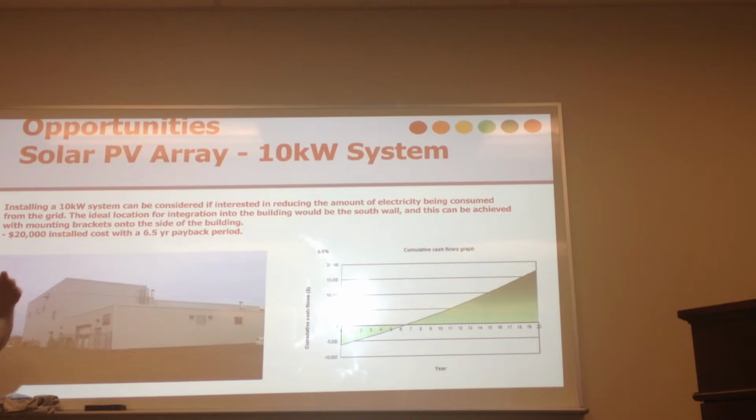And then, like I said, what did you calculate yesterday? Capacity factor. For your information, these people are going to love to hear this: the capacity factor on the panels at the CAST building is 11%. We've used a similar number in this analysis to determine our payback of blank. Or I think a better way for solar is internal rate of return.